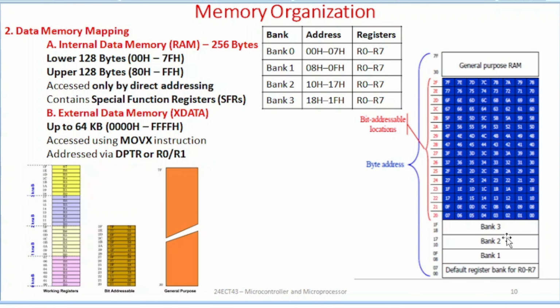Since the addresses 00 to 7FH are the addresses of RAM memory, the SFRs have addresses between 80H and FFH, but not all the address space from 80H to FFH is used by the SFRs. The unused locations are reserved and must not be used by the programmer.